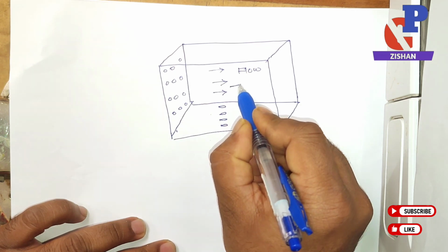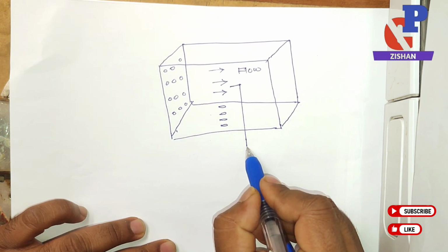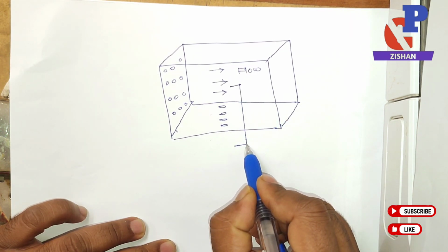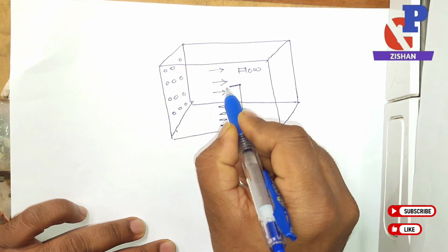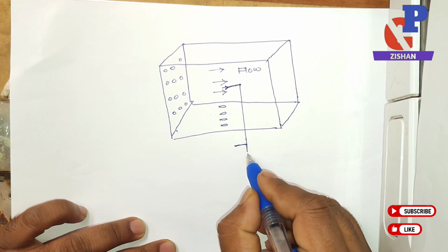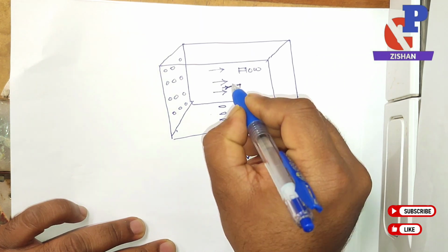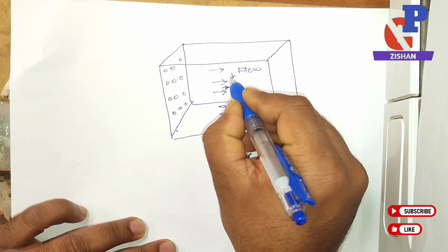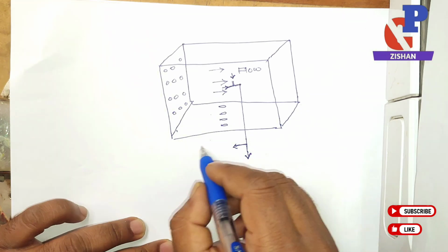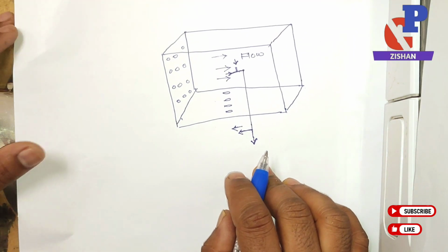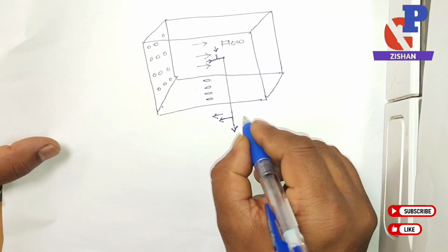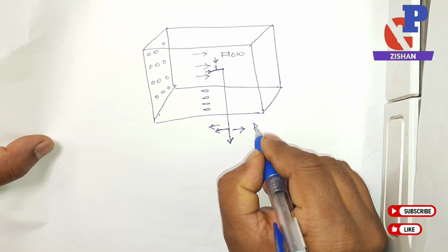We have to connect the static pitot tube through this direction. That arrow line gives you the dynamic pressure inside the duct, and the tangential one gives you the static pressure inside the duct. For the velocity we have to take a reference point, we cannot take velocity directly.